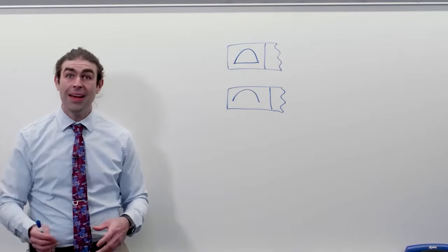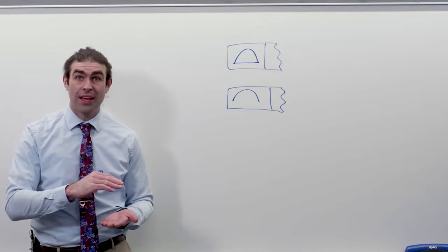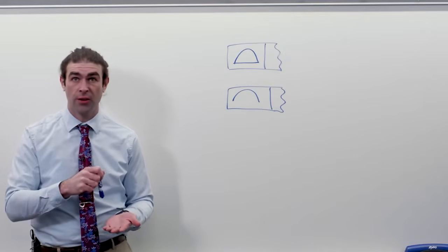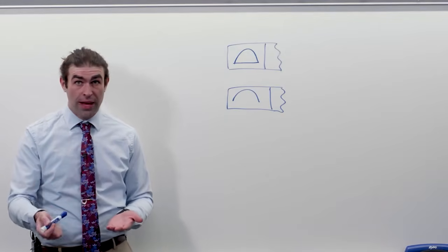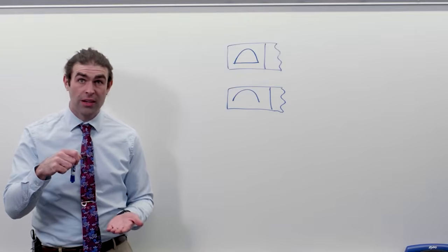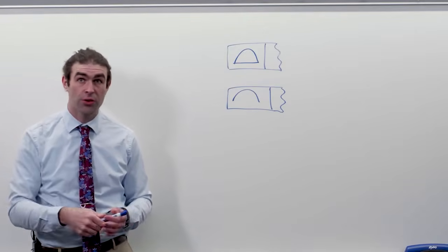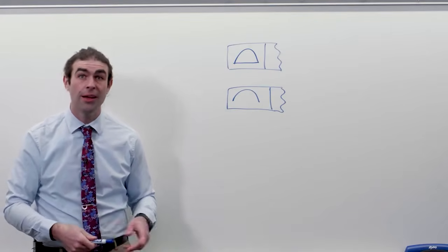If you recall, when you apply flatness to a surface, it controls that entire surface. You have to run your indicator left and right along the surface. With straightness, if you applied it to a flat surface, you only have to run your indicator in one direction, an individual check. So you could essentially have a corrugated part in the other direction.